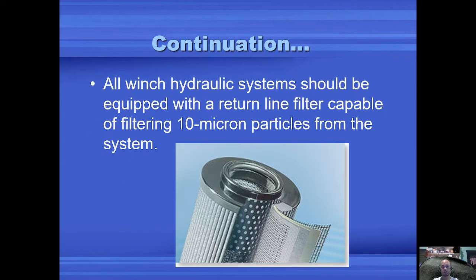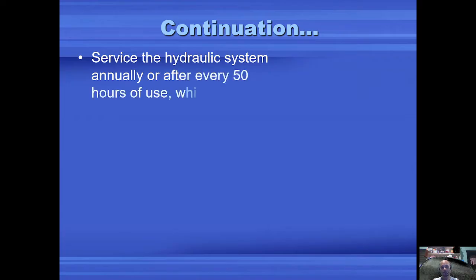All winch hydraulic systems should be equipped with a return line filter capable of filtering 10 micron particles from the system. So it's very small, 10 micron. Service the hydraulic system annually or after every 50 hours of use, whichever comes first.